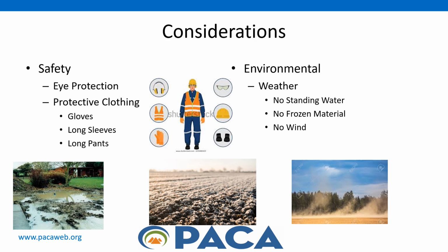As always, safety and environmental considerations must be examined. The cement soil stabilized material should never be mixed with standing water or when the soil or aggregate is frozen. Cement soil stabilized material should never be mixed when the air temperature is below 40 degrees Fahrenheit. It's further recommended that the dry cement should not be placed on windy days.